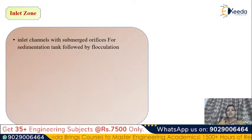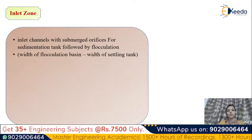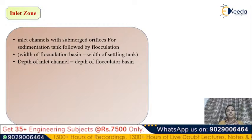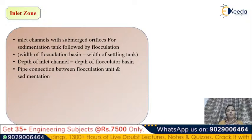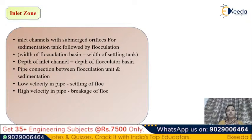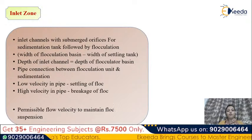Again, the inlet channels with submerged orifices for the sedimentation tank, followed by the flocculation in the secondary sedimentation tank. In that, the width of the flocculation basin equals the width of the settling tank. The depth of the inlet channel is equal to the depth of the flocculator basin, and the pipe connections between the flocculation unit and sedimentation. Low velocity in the pipe in case of secondary sedimentation is for settling of floc, and high velocity in the pipe is for breakage of floc.